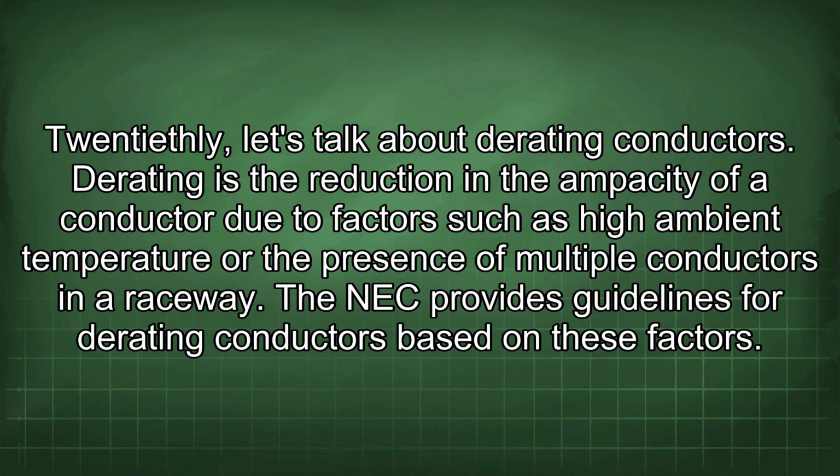20thly, let's talk about derating conductors. Derating is the reduction in the ampacity of a conductor due to factors such as high ambient temperature or the presence of multiple conductors in a raceway. The NEC provides guidelines for derating conductors based on these factors.